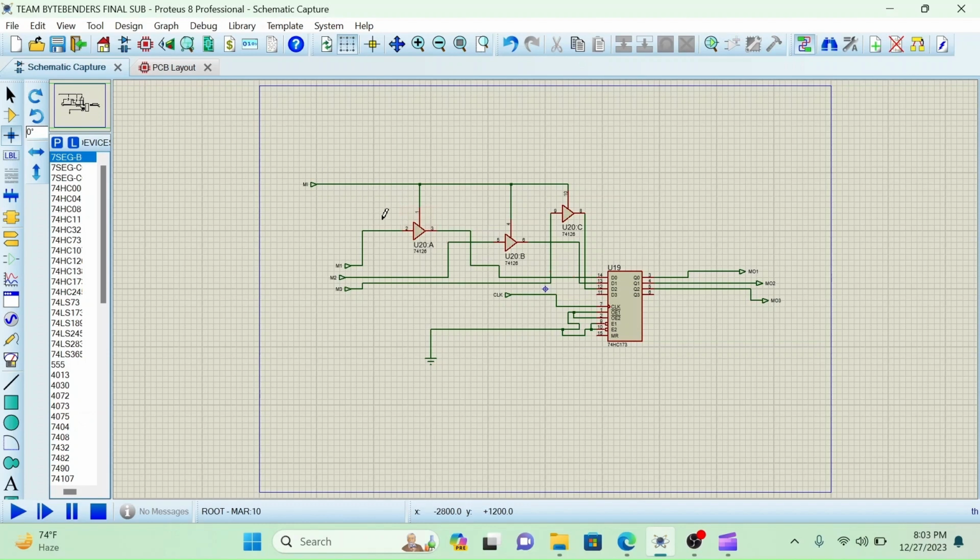The MI and the inputs are connected through the tri-state buffer into the D flip-flop. This is so that no data is stored if the MI is not activated. Basically, it is to control the storing of data into the MAR unit.